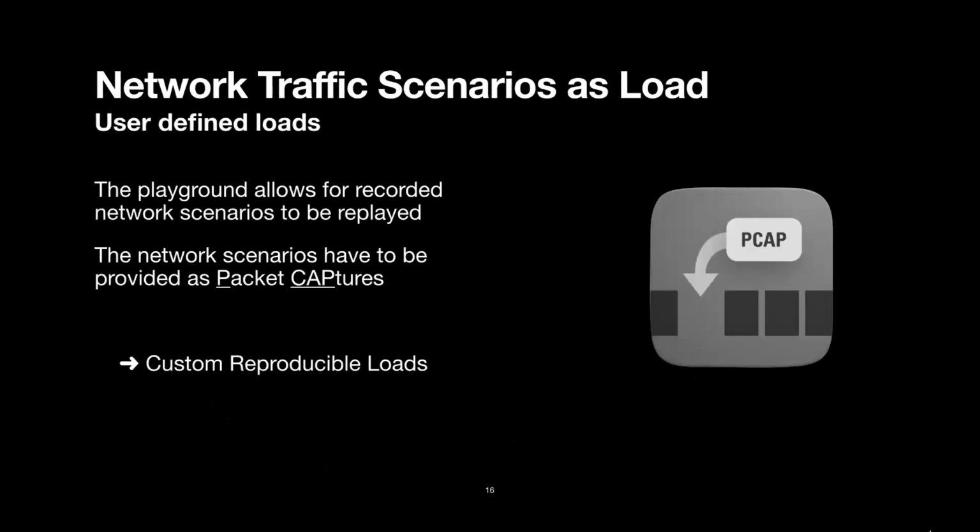The user-defined loads are also possible. Our playground allows for recorded network traffic scenarios to be replayed, and those network scenarios have to be provided as packet captures. These packet captures can be parsed by a script provided by us to the inter-arrival times, and these inter-arrival times can then be automatically integrated into the code. This allows for custom reproducible loads, but the PCAPs have to be of a sensible size, obviously, because microcontrollers only have limited memory. So the PCAP size has to fit the memory of the microcontroller.